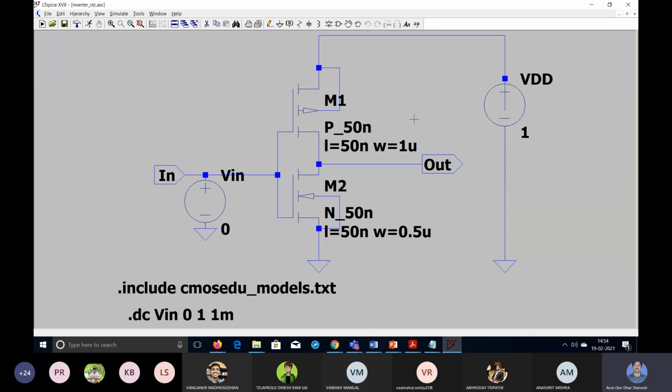Therefore this is done like that, and we have also provided the highest voltage, the supply voltage VDD. VDD is 1 volt. VDD is connected to this source, and also the body of the PMOS is connected to the highest supply voltage, because in this circuit we can see for the NMOS we are connecting the body of the NMOS to the lowest potential point, and the body of the PMOS we are connecting at the highest potential point of the circuit. For this complete circuit, this is the highest potential point, that is 1 volt, and the lowest potential point is ground, 0 volt. So this body is connected to the lowest potential point at the ground, 0 volt. For the PMOS, body is connected at the highest potential point, that is 1 volt potential difference with respect to ground. So it is the most positive, most highest potential. It is just relative. So relative to others it is highest.